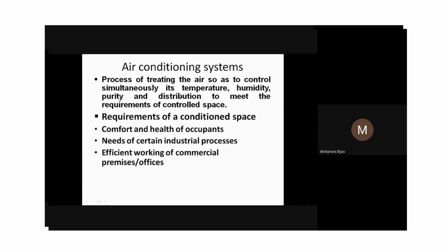The hot vapor refrigerant at high pressure and high temperature is entering into the condenser. There are three cases: we use some external cooling arrangement. If it is a moderate capacity refrigerator, we need to use a fan. If it is a small capacity refrigerator, no need. Low humidity and high atmospheric humidity will not give comfort for us. Only moderate humidity will be giving comfort for us. What is the meaning of humidity? Humidity is nothing but the amount of moisture in the air.